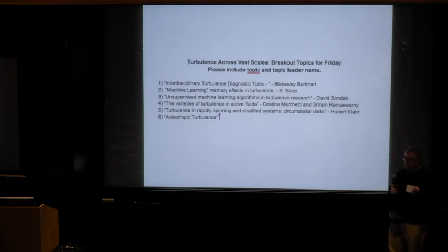What is really important is the amplitude. I think the physics of the spectra is in the amplitude and not in the slope. In this case, as I showed yesterday, we have Kolmogorov part and steeper part, which is determined by Coriolis parameter, and they affect each other. And if you just take a point somewhere, you don't know what gives a big contribution to this point. Is it coming from Kolmogorov part or from the steep part? But if you compare the whole amplitude for different wave numbers, then you can learn much more from the spectrum. And I think this is a general conclusion which goes beyond application in geophysical fluid dynamics.